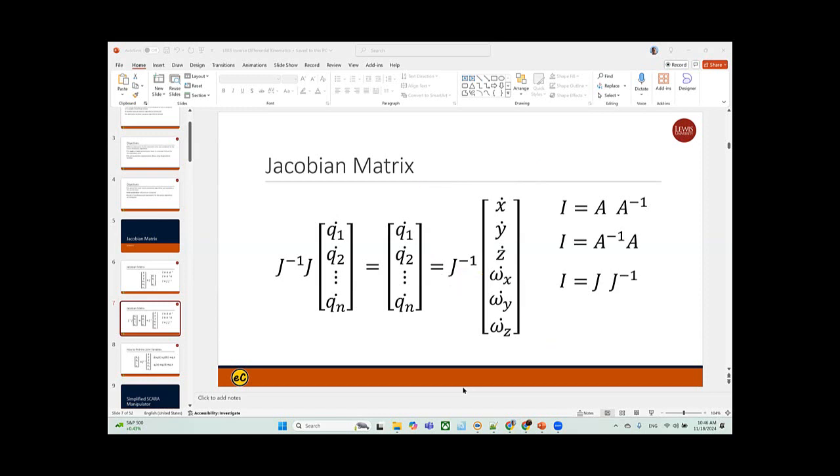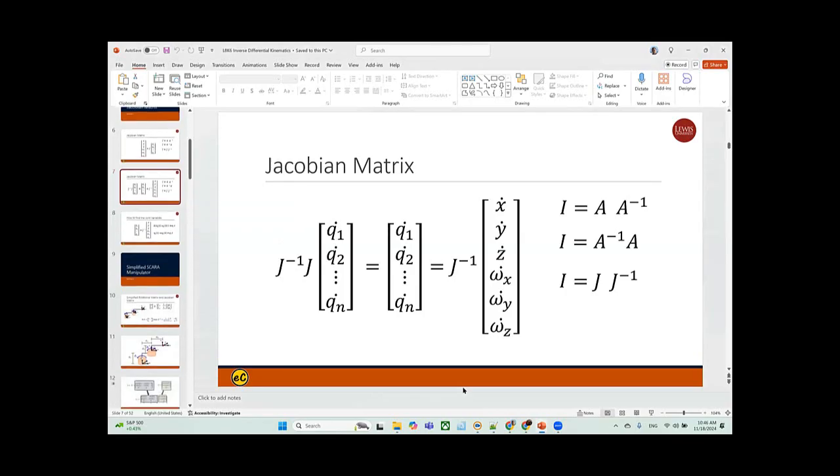Okay. So forward Jacobian is based on the state variables that you know, to control where you will go, that is your destination. Okay. And then inverse Jacobian is you go from your end effector's expected location and speed backward to see how fast your control variable should be. Let's call it inverse Jacobian. Okay.